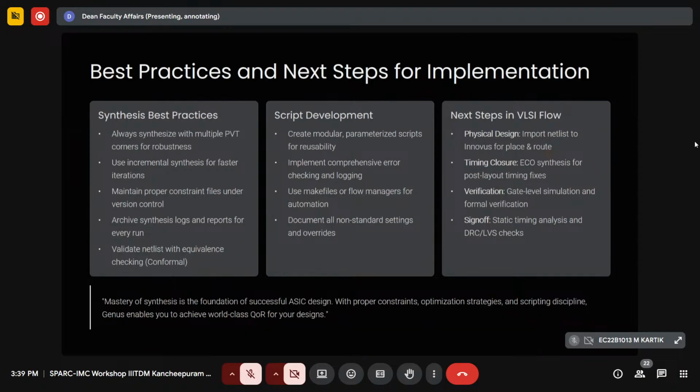They have a memory compiler. We need to go through that memory compiler process and generate a .lib, and that .lib is provided to synthesis. The .lib will have all the timing information, how each bit of the memory is there, and the timing information is taken through all the stages. So it will be kind of a macro. Memory will be a macro. The memory compiler is used to generate this. They come under custom design, full custom design, memory design actually.